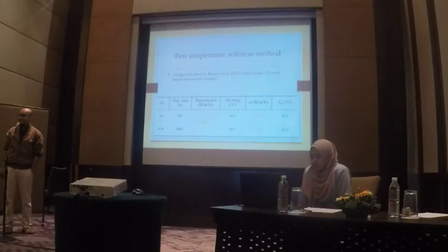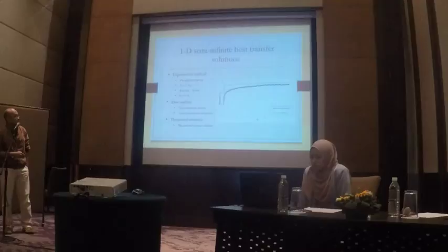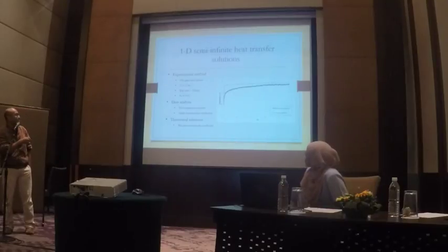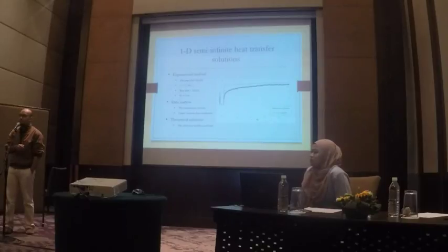Another one: what is the range of the Reynolds number? You mentioned 27 meters per second this time. I'm sorry, I cannot remember the Reynolds number for this. Is it in the laminar region, the turbulence region, or the transition? Well, because we are using a transient mesh heater at the inlet of the experimental tunnel, the flow will be turbulent from the get-go.